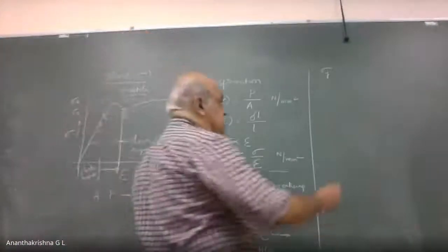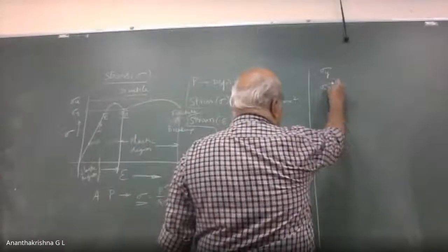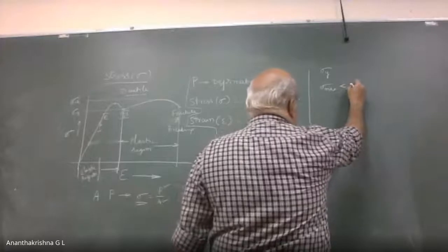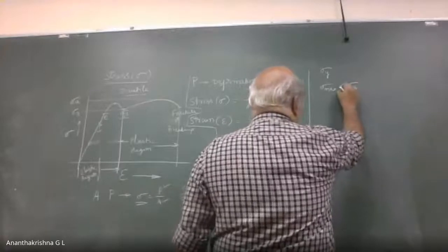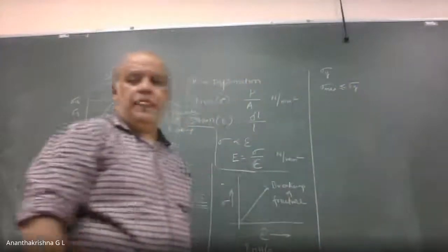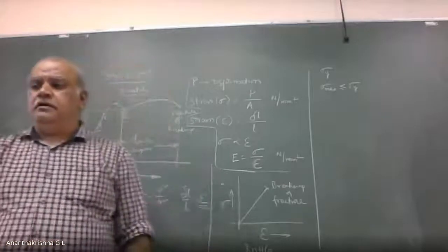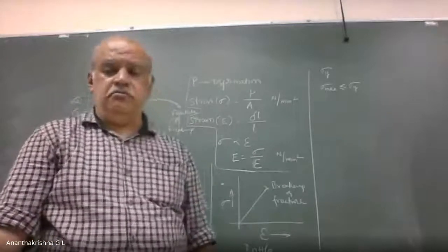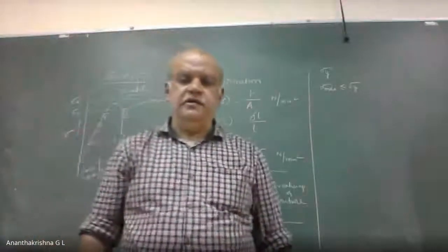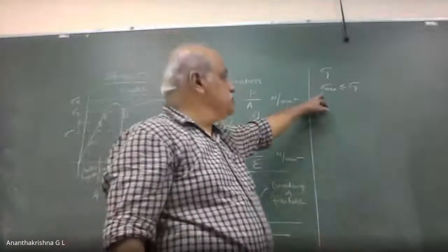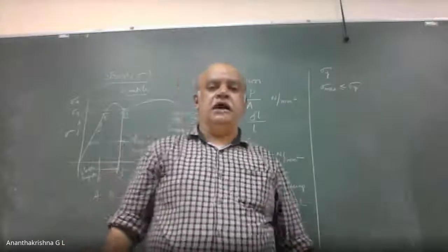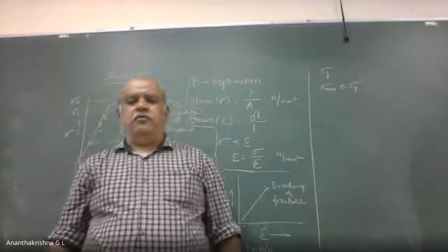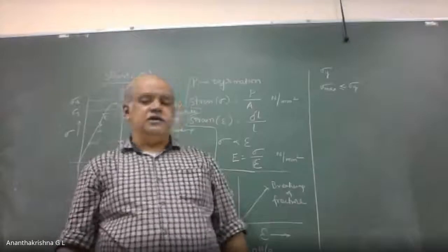That means the maximum stress induced should be less than or equal to the yield stress of the material for safe design.